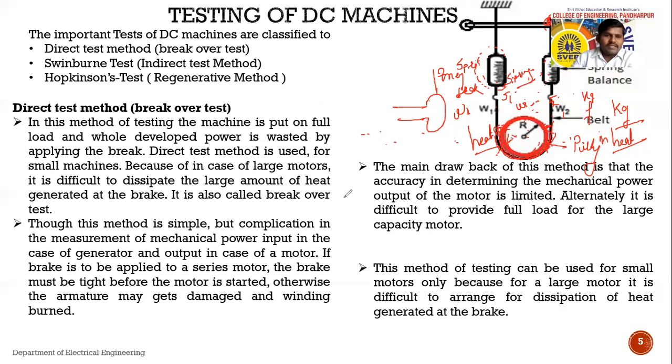So it is also called the brake test. Sometimes if the heat generated is more, the belt may be damaged. So it is not possible to perform such a test on a large size motor or a big size machine.